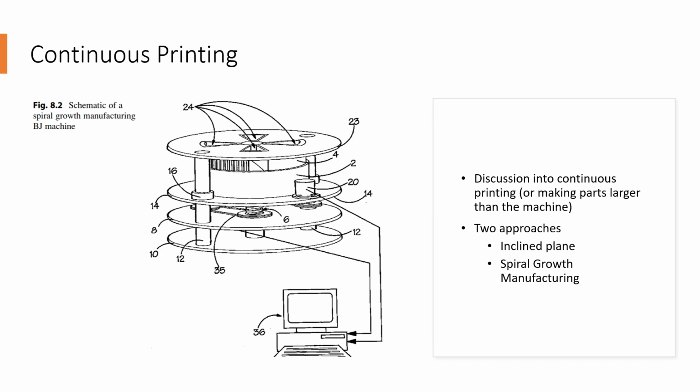The second approach utilizes a circular powder bed with constant rotation and continuous binder printing and recoating. While in motion, the powder bed moves down the spiral continuously to make room for the next layer. Moreover, the top layer forms a spiral in the powder bed. There are also several build stations that each contain a print head of multiple nozzles. A side effect of this design, however, is that the print must be pre-skewed to compensate for the differences in speed from the outside and inside of the powder bed.